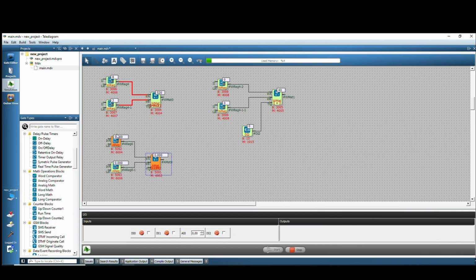Let's give an example of low limit. It is selected inside with low limit. Since I connected a block externally, I do not enter a value inside. Low limit serves this purpose. For example, we entered the value 80 and let's give the INA value in turn. When we give the value of 100, it will take the value of 100. That is, it will transfer any value change above 80 to the output.